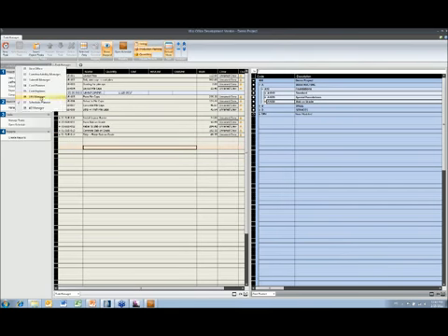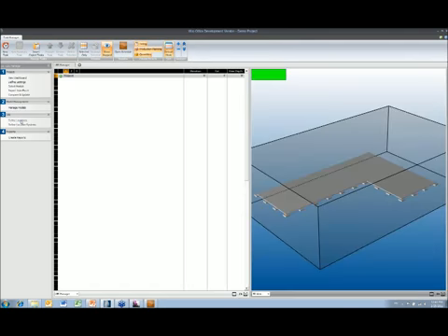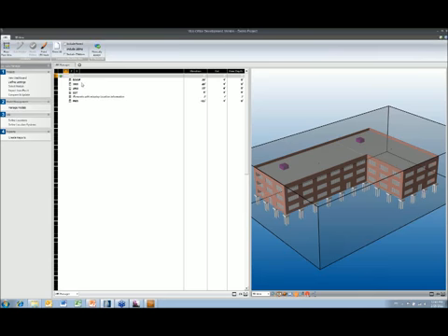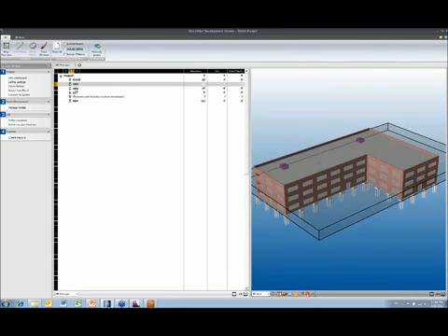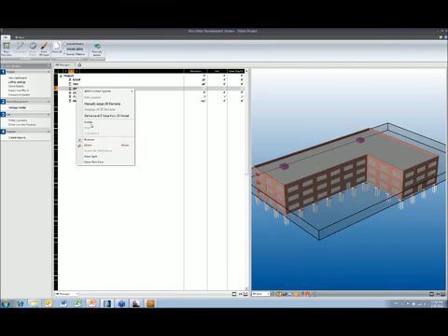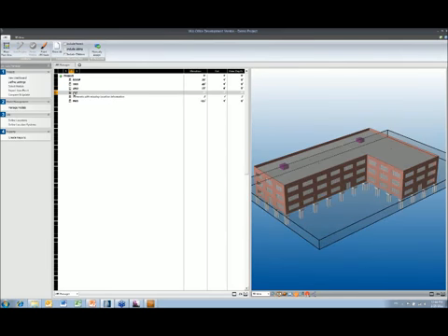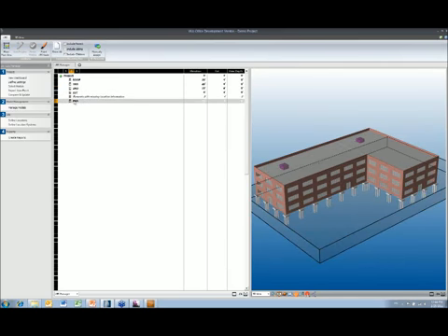Okay, and then now to create the locations. I've only got substructure, so I'm not going to create location systems because there's only one. But I go to define locations. So even though I've got the whole building there, I'm only going to work on the substructure at the moment. So now we've got floors in here, and we can isolate them, you can see exactly what's on each floor. And now we want the actual zones.